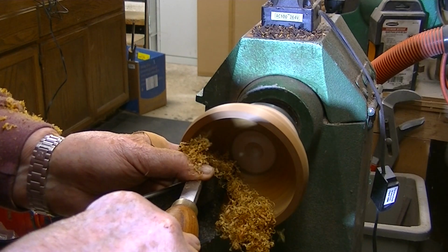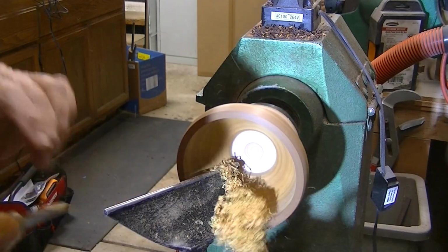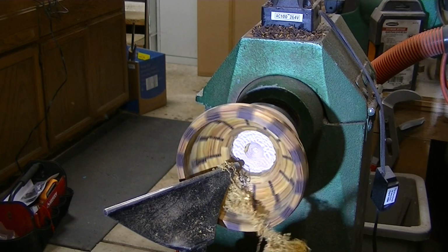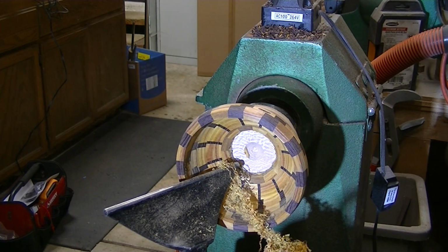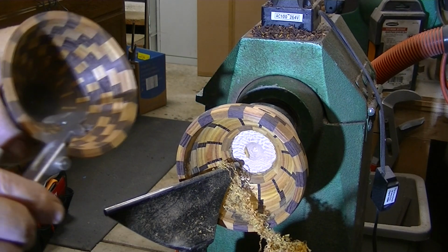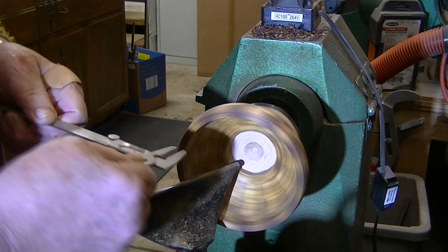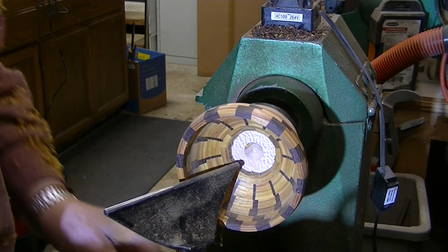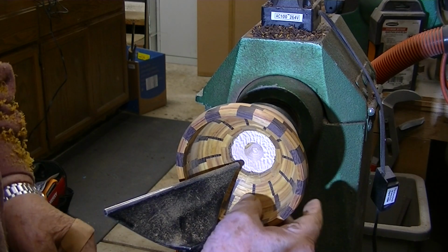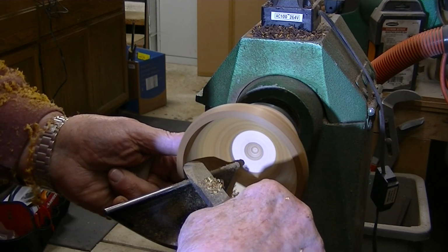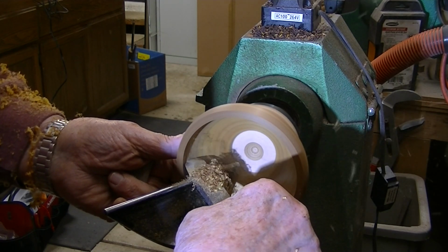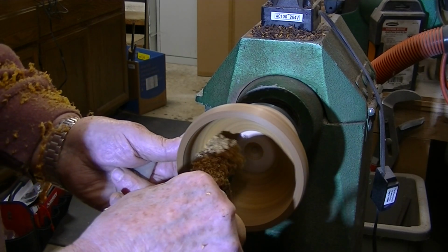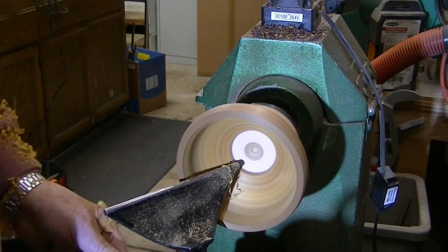Scrapers cut less aggressively on the pull than they do on the push, and so some of my final cuts on the inside of this thing are from the top where the glue block is to the center. I am checking the wall thickness of the base to be sure that the top will have the same thickness. So when the joint is connected, the inside edges will also match up as well as the outside. If they don't, I'll have to go in through the opening and fix that, and that's not something I prefer to do. Here I'm doing my final cuts on the inside of the top with a commercial scraper.